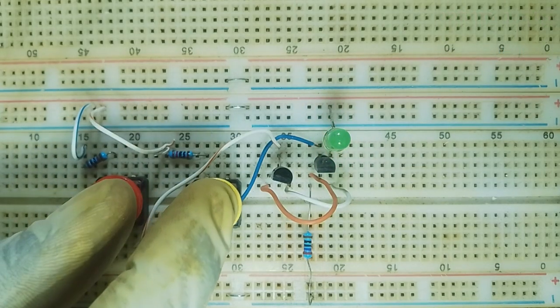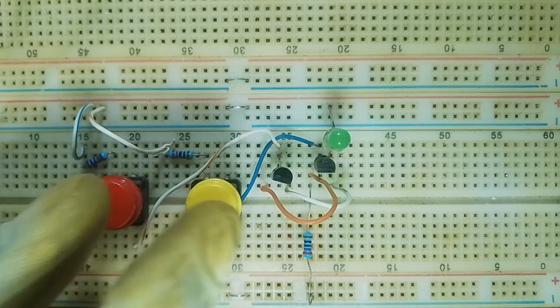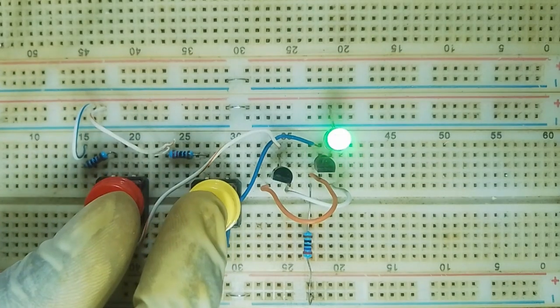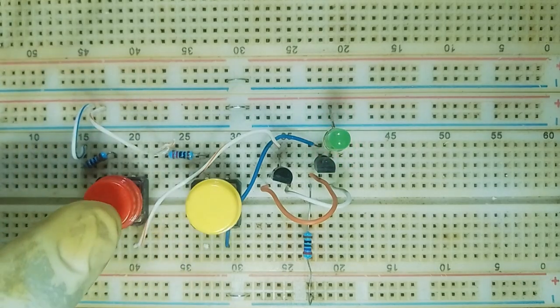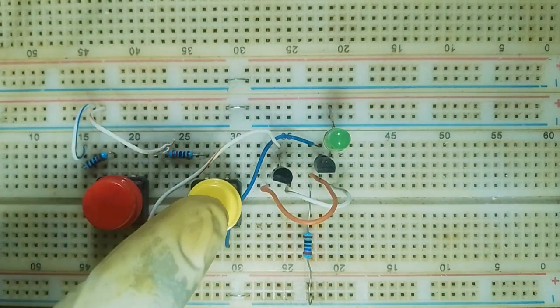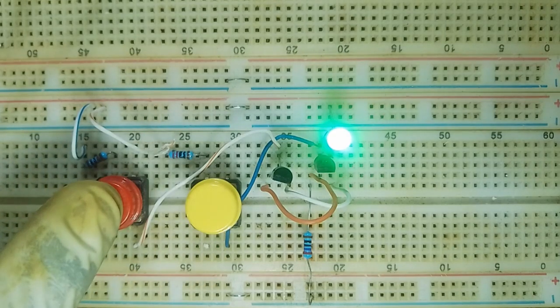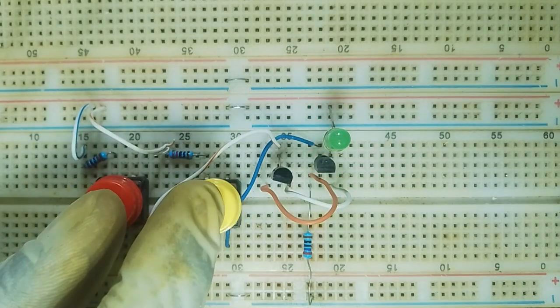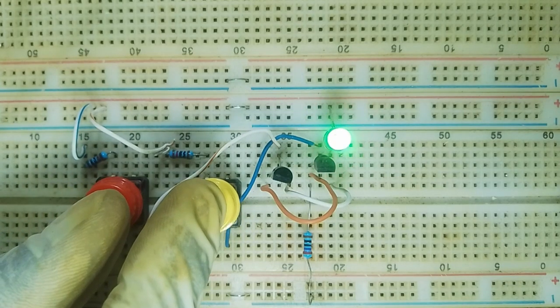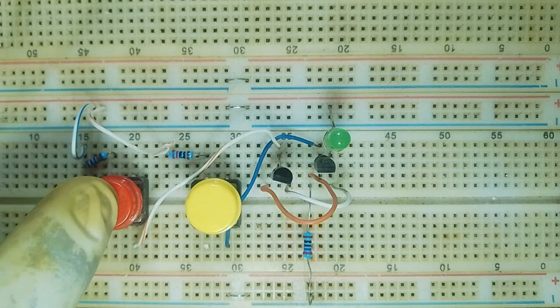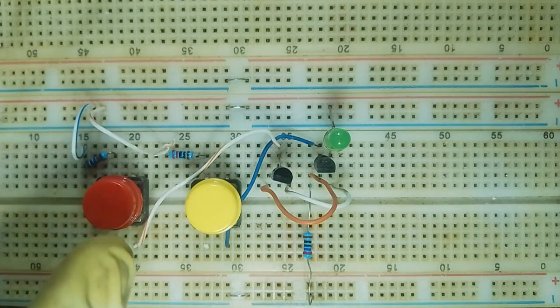In today's project, we are going to build logic gates using transistors. Ideally, logic gates are all available as an integrated circuit. These chips are inexpensive and often have 3 or more gates in them. However, there are times when your circuit requires only one logic gate. This makes it sound better to simply build one with transistors instead of using an entire chip. Or, let's say the logic gate chip you want to use at that moment is not available.